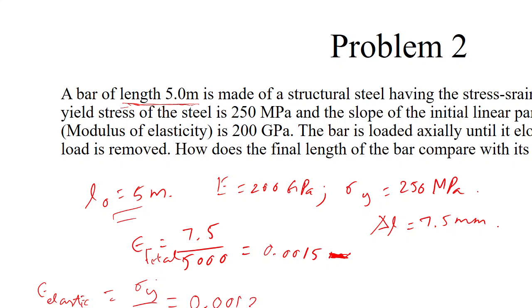Which is 0.00125. So from this, what can you infer? The total strain is greater than the elastic strain, right? Yes. So what we can infer is that plastic deformation has occurred.